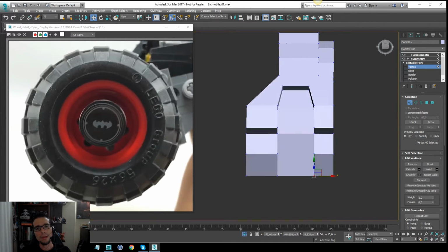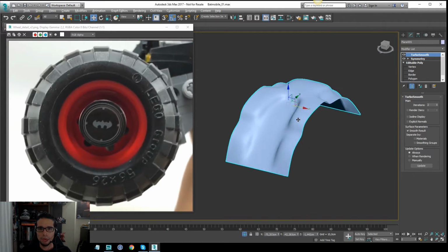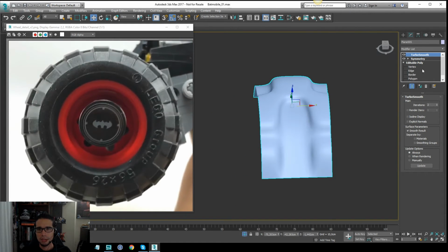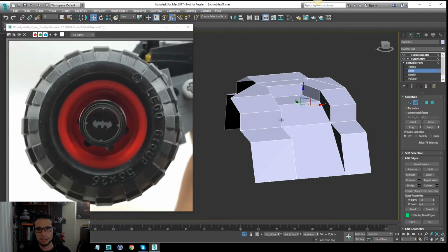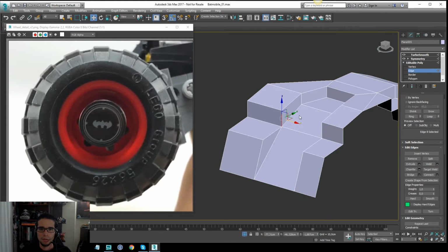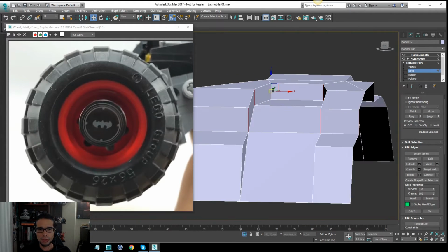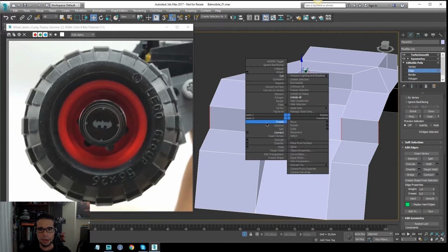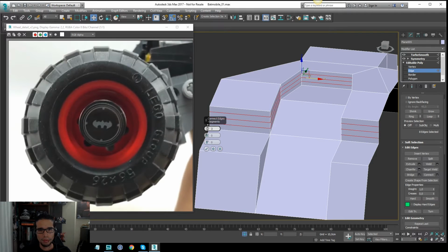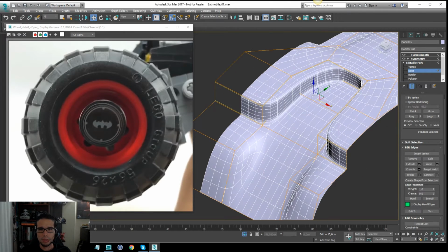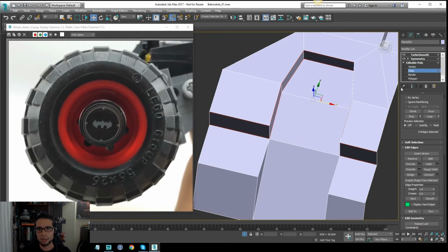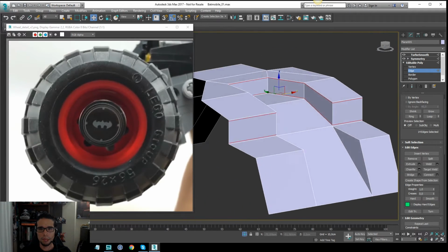Okay. So what I was talking about is I need to avoid this smoothing effect it is having right now, and the way to avoid this smoothing effect is creating subdivision near to the corner. So right now, for example, if I have this and I create two different connections, one near to the top edge or to the top corner, and one in the lower corner. So if I apply the changes, you can see now it is more sharpened. This is going to solve one of our main issues.